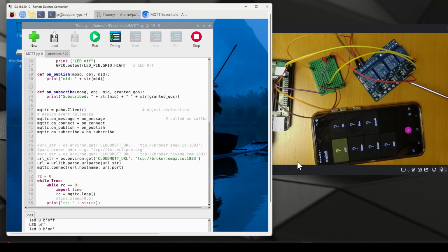For the command part, it's isolated from the other side, for sure. We use 5 volt and 3.3 volt here. On the other side, these are all relays, so you can connect them to any devices less than 10 amp, even AC 110 or 220. And you can build this circuit with any other kind of board to control your devices at home, in your office, or in your factory, wherever it is.